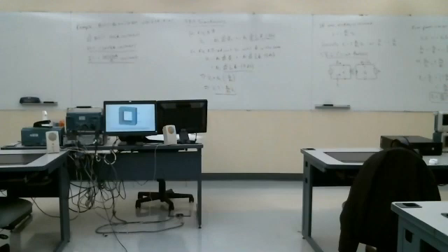The other one, the only other formula you need, is this power convention formula. And again, this is the one we used in circuits. He has a minus sign in the one over there, and that's because the current is in a different direction, the I2 current. I prefer the circuits convention: power delivered to the primary, power delivered to a load.